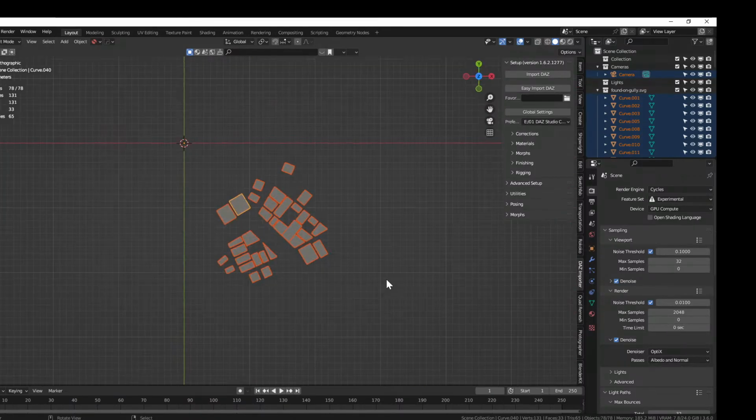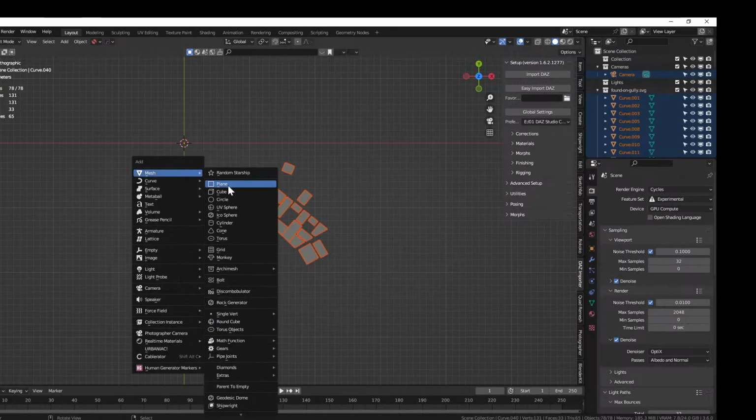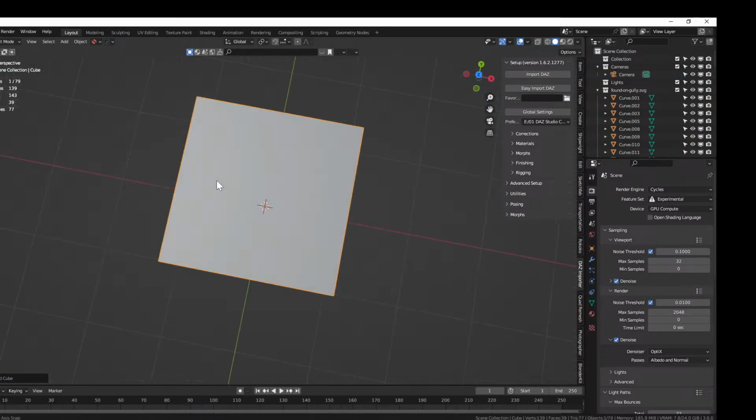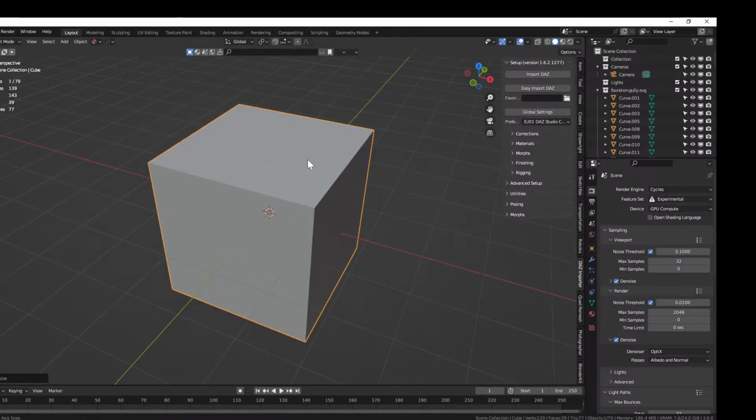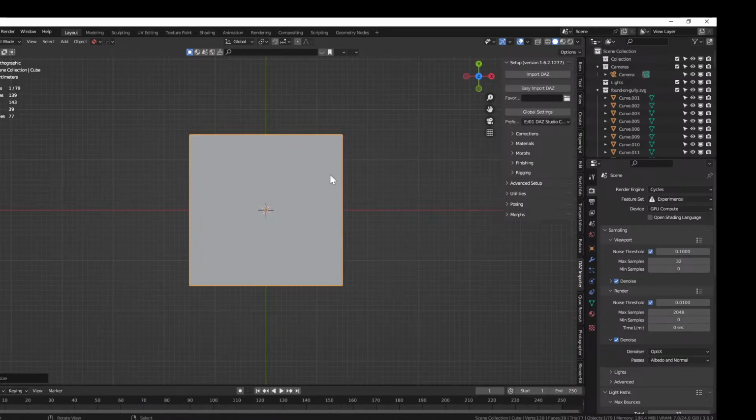So let's set our scale up. I made my village with, they called it a river, but I'm going to use it as a big road down the center. And we can just decide on a scale for a road. I think I want Shift A. I'm just going to make a cube. And that's 2 meters. Let's scale it up to, let's do it this way. S 1.5. I made my building kit mostly based around 10 feet. So that's a good size for it.